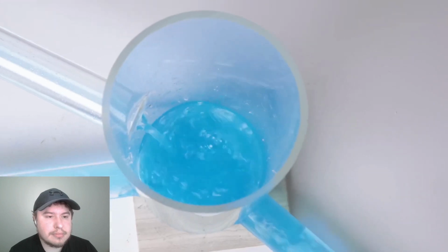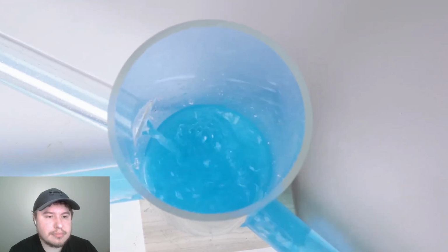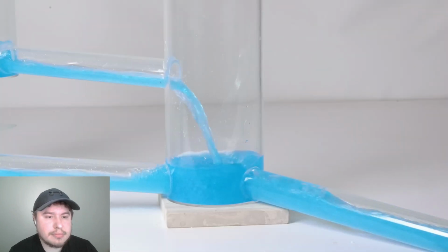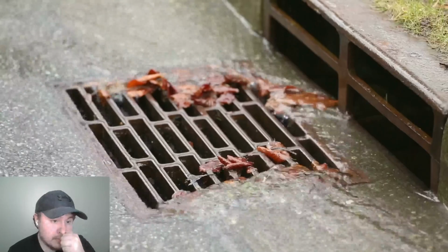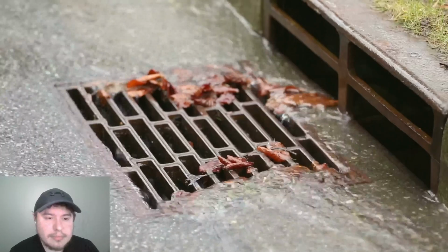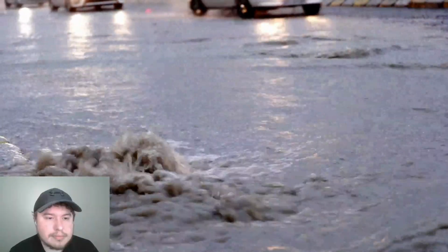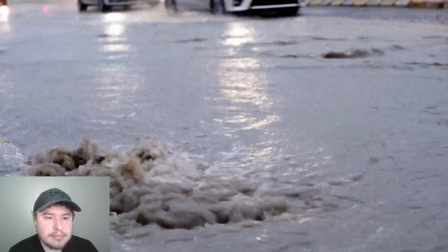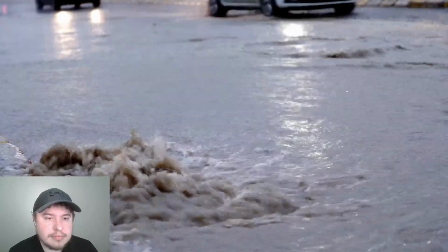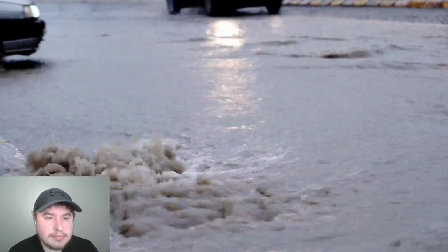The manhole acts kind of like a buffer, smoothing out flows through the system. In normal flows, that's not a super important job. It's basically just a connection between two pipes. But the peak flows for most sewers, even if they're not storm sewers, happen during storms. Drains may be improperly connected to sanitary sewers. Plus, surface water often finds a way in through manhole covers and other means.